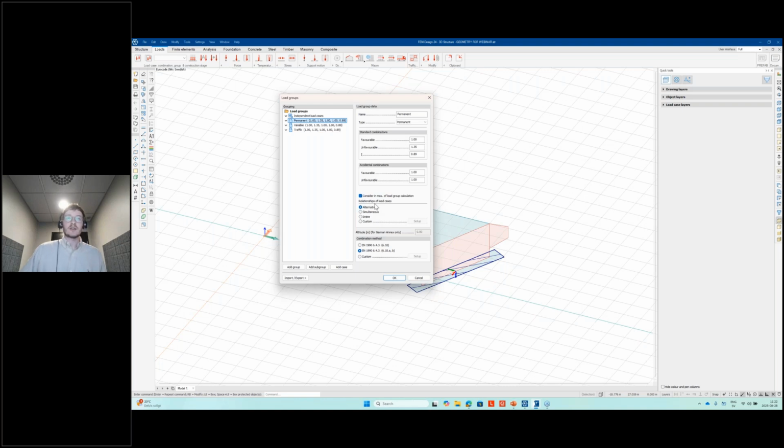Oh, actually, I can maybe save the logic until later. I will just show you how to create some load cases first. So in my example, I will use some dead weight of the structure. For type, you have to go in here and create the plus sign plus structural dead load. The plus sign means that the software will automatically apply the load in your model.